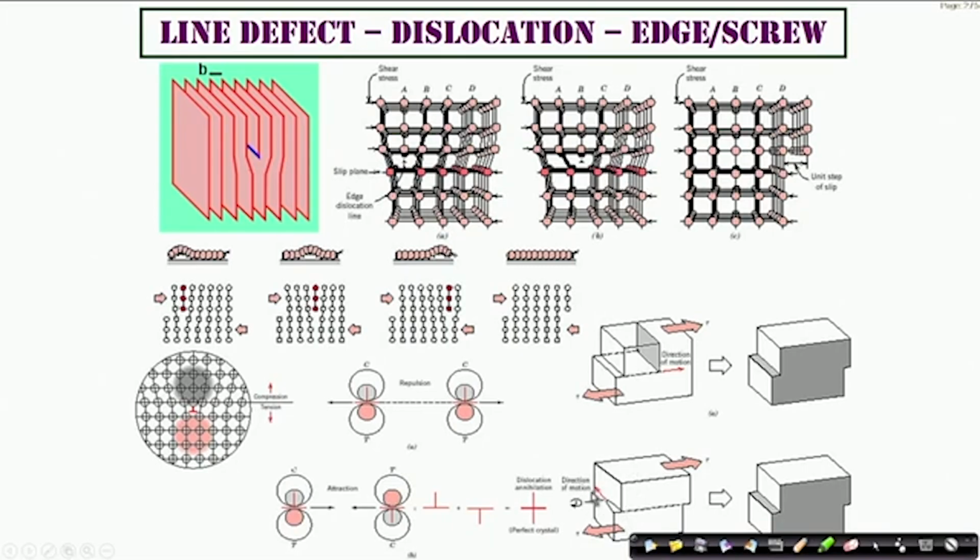If you imagine a helical path around a particular line, which happens because of the twisting or shearing of the crystal along this axis of rotation, then this is how you create a screw dislocation. So essentially we have line defects, either as edge or screw.